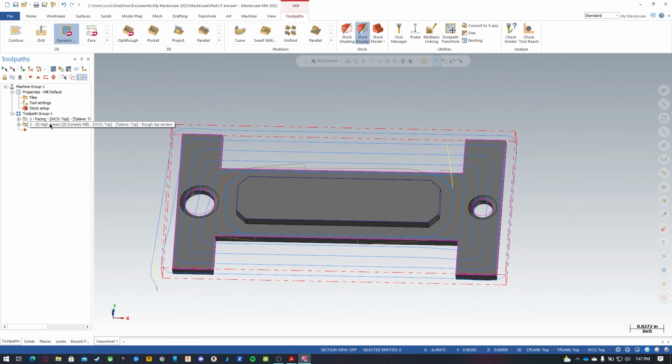Now this is all dependent on your feed rate and your depth of cut. If you have a really fast feed rate and a large depth of cut, so using the full length of the end mill or the flute, you might want to go 30 thou step overs, but 150 inches a minute. Whereas we're doing a shallow step over or step down, and we might as well just go 60% of the actual cutter width. Okay, we can go 61 inches a minute. That should generate a decent cut.